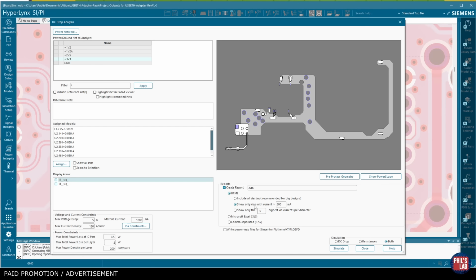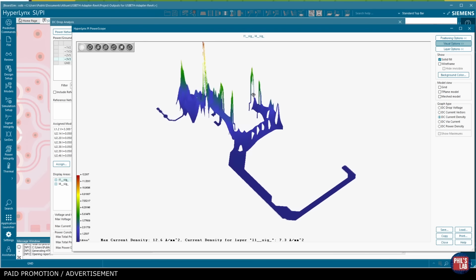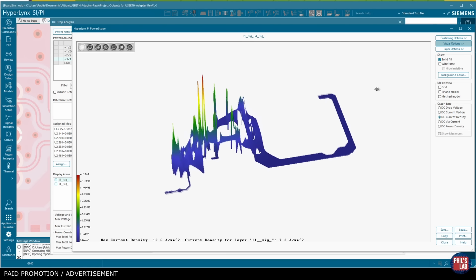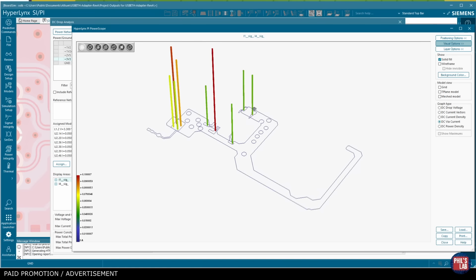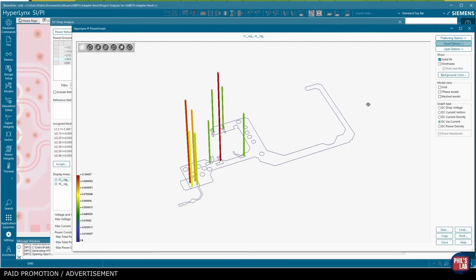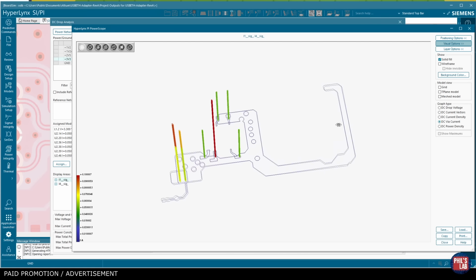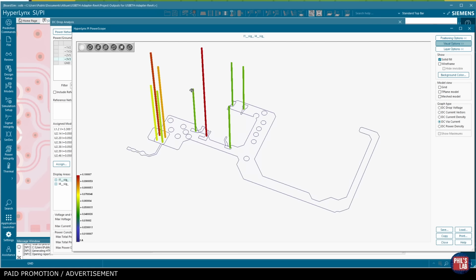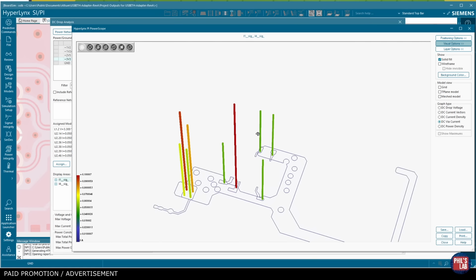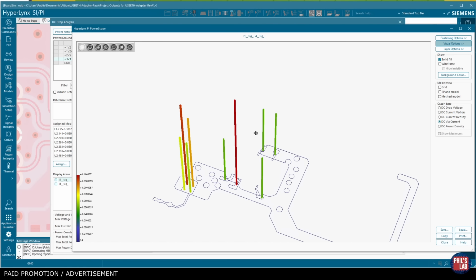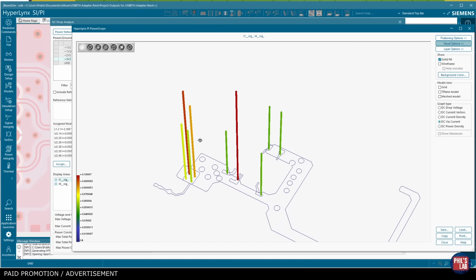Performing DC drop analyses is incredibly important to make sure you stay within certain voltage ranges and levels, but also that you don't exceed current densities within your design, which could cause thermal issues and failures. It also lets you analyze and optimize the placement of your traces, your sizing of polygon planes and pours, as well as how many vias you might need to distribute current and power throughout your design and how that current and power is actually distributed within these various vias, traces, and planes.